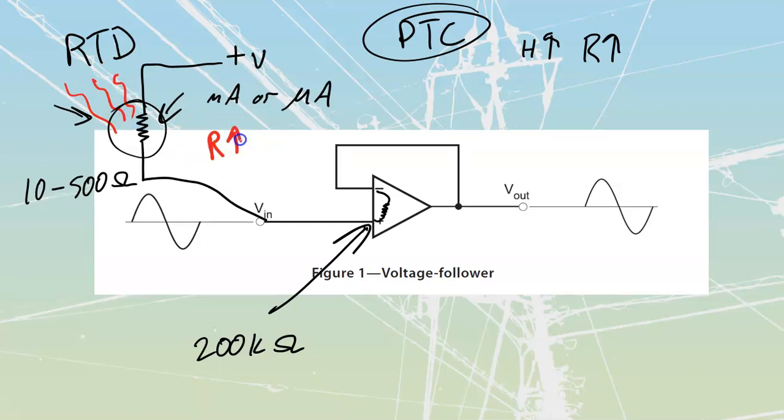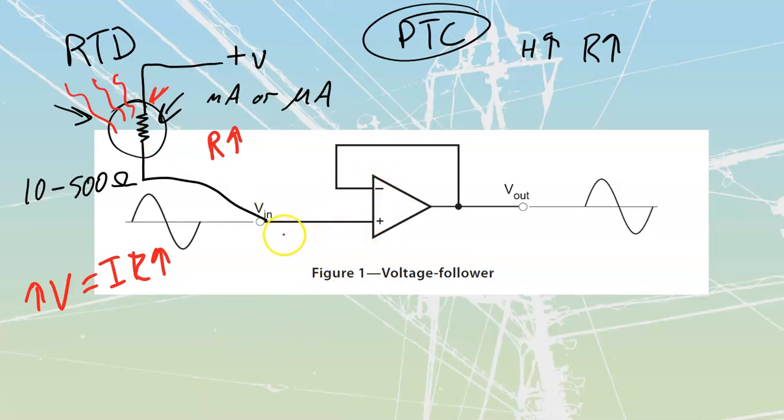our resistance goes up. If our resistance goes up, then since V is equal to I times R, the amount of volts that I'm going to drop across it is also going to go up. Because my resistance went up, my volts have gone up. If the voltage drop across here has increased, that would mean we're going to have fewer remaining volts over top of this circuit back over here, which means that I'm going to see that as a decrease in my value of voltage. It's going to be a dropping value of voltage.